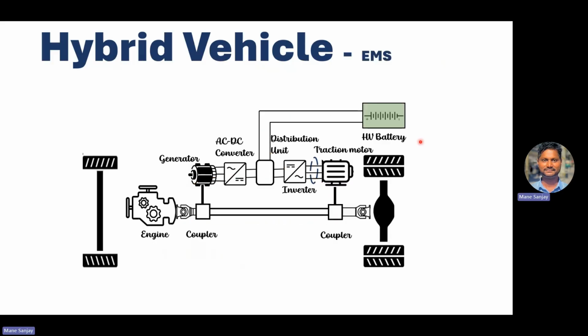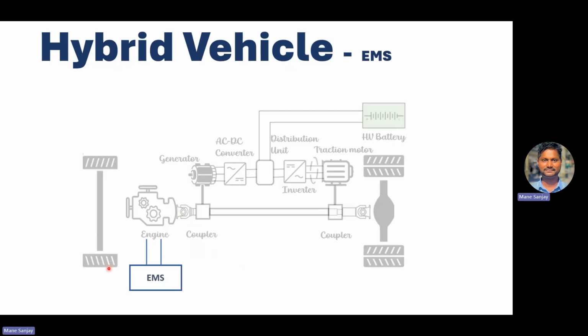Going to the components, when we talk about the engine management system, this is the engine management system ECU. It takes a lot of data from the different sensors: manifold pressure, throttle position, camshaft position, crankshaft position, everything. It takes the input over CAN, or sometimes through a direct hardwired connection from the sensors. It controls the engine operations.